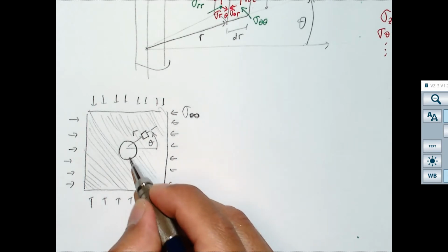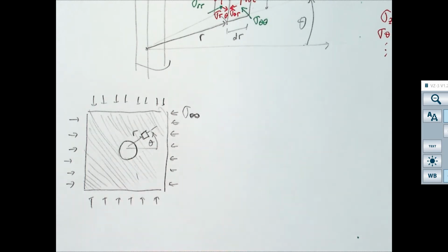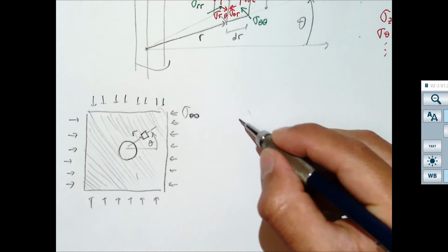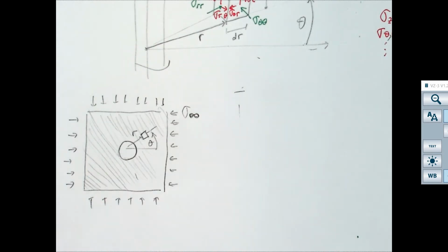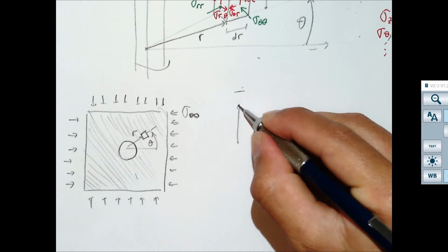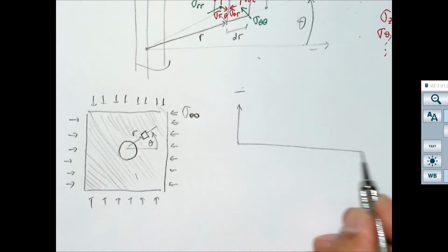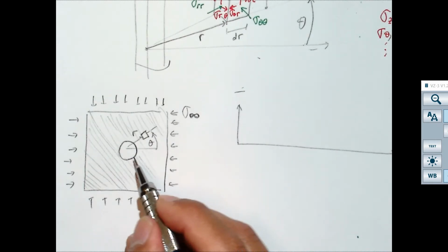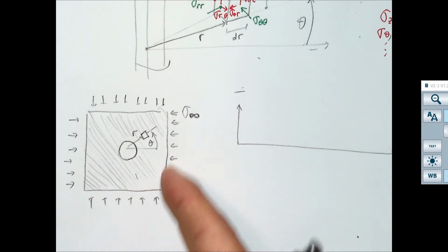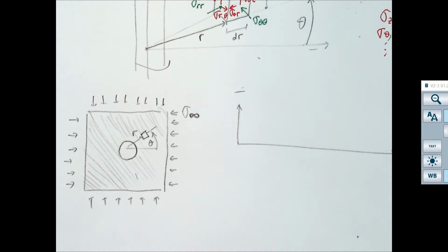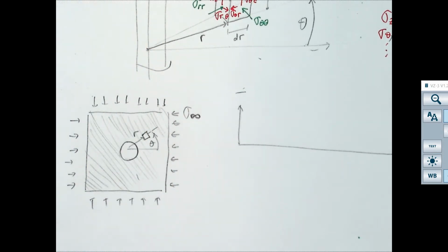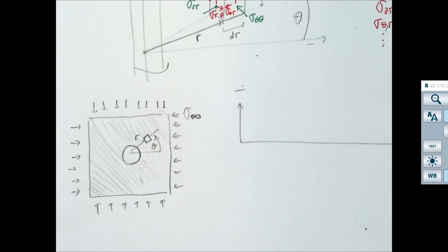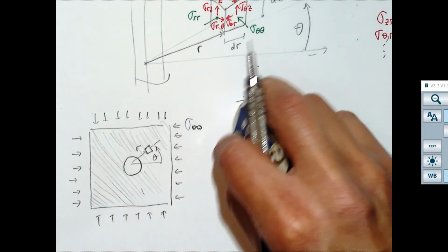Here, the radial stress around the wellbore. And if there is nothing acting on it, there is no fluid, there is nothing in it. This is just a cavity. This is just a solid. I made a hole and I'm loading it around that, similar to this, but I'm loading it in all directions. What is going to be the stress on the wall of the wellbore?